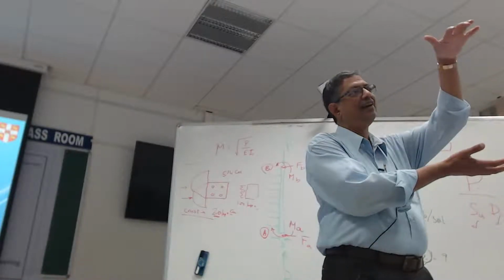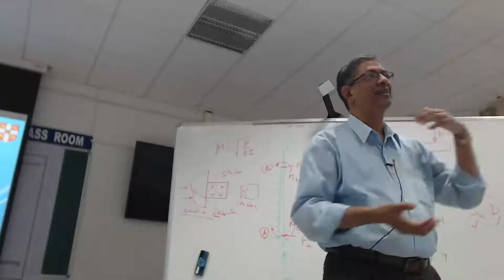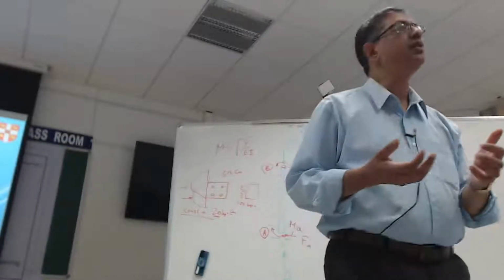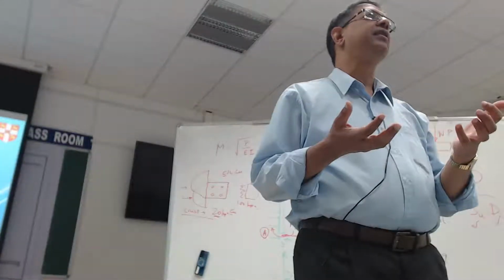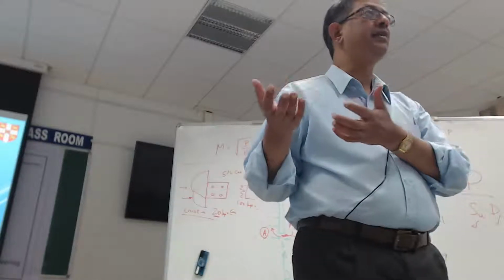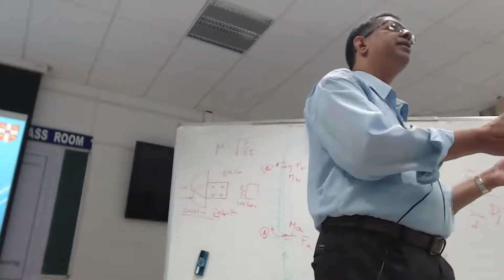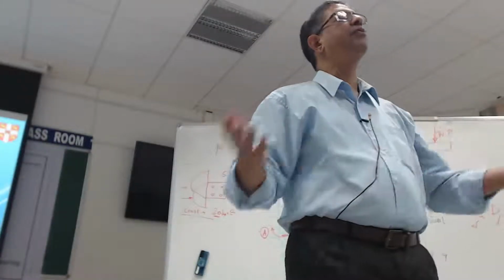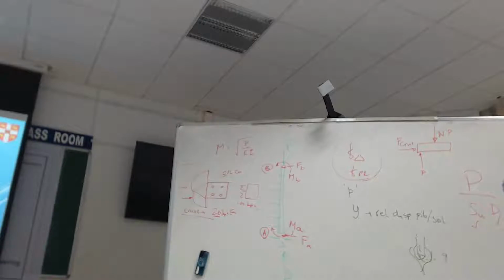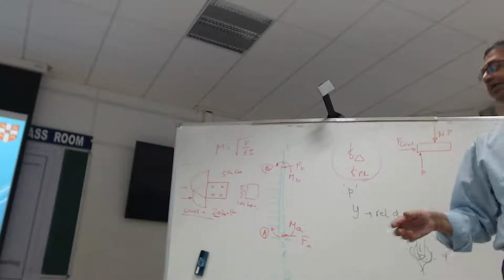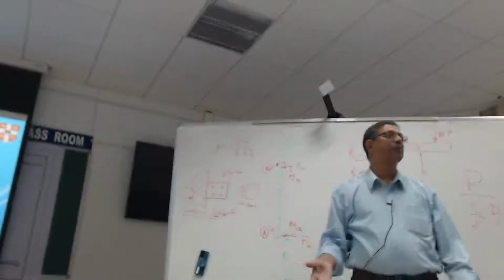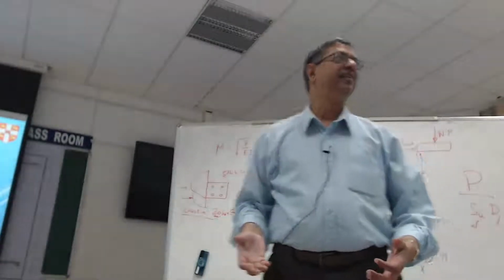So you've got all this dry sand on the top, which is all going to act exactly like the non-liquefiable crust. That is the situation I worry about most, because we're not very good at thinking of water table changes. Designers have assumed that the worst case is always when I have water table on the surface, because then I'll get full liquefaction. But in this case, actually having the water table lower causes more trouble. And imagine this is all sand coming at you. Sand can apply so much more passive pressure compared to clay. So you need to be aware of that.